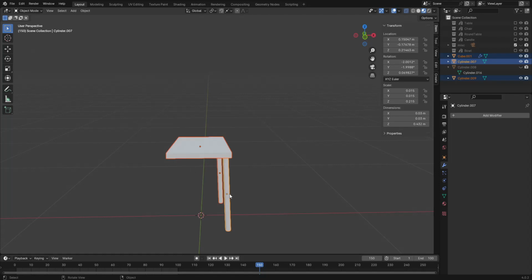The orange one is the one that keeps its point. As you can see, since I've joined the objects now, the front foot was orange and it did keep its point. You should also have recognized that the second half of our seat is missing now. This is because the mirror modifier was part of the seat, and we used the front foot as our base object, and this one didn't have a modifier.